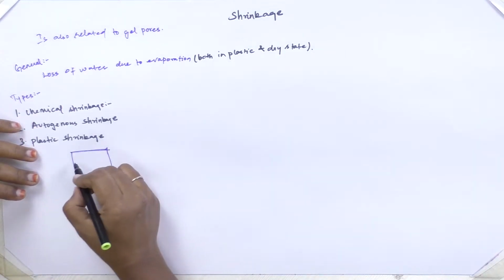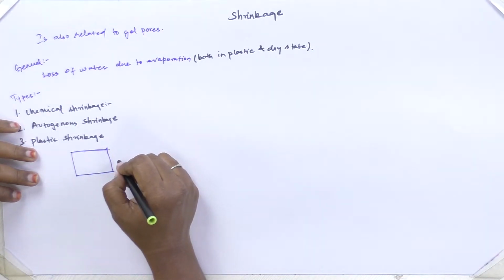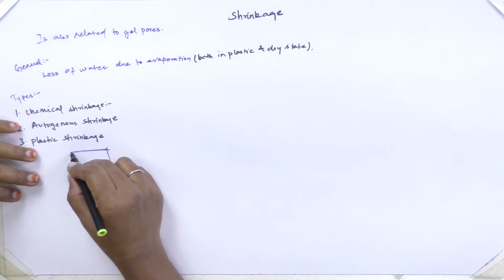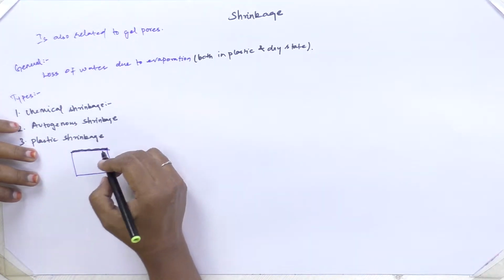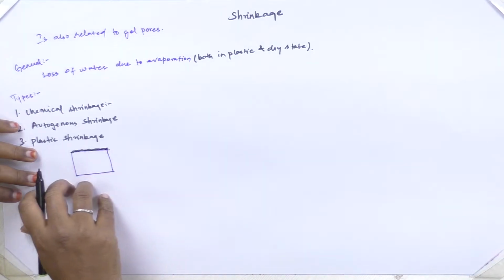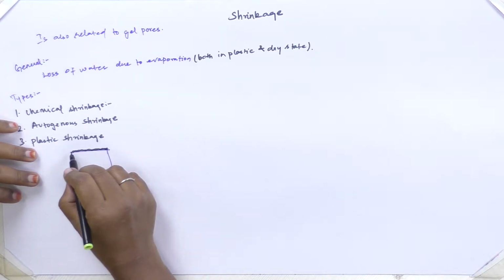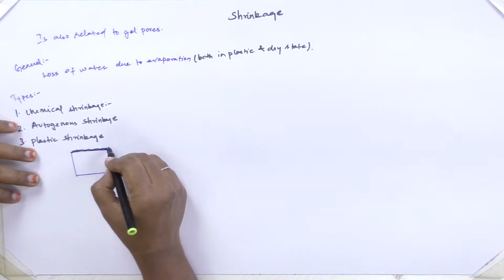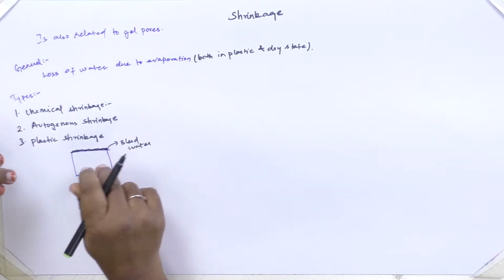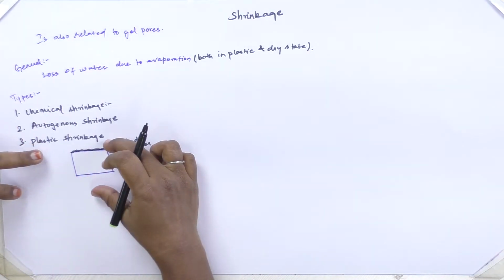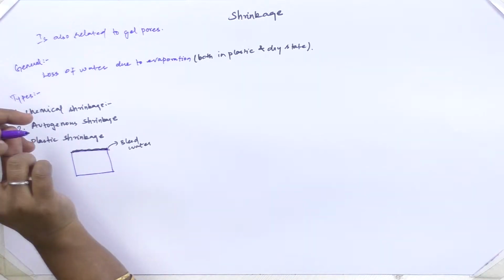After concreting, because of having a low specific gravity, the water will move up, leaving the aggregates and cement paste down, and if this bleed water gets evaporated, then there occurs a plastic shrinkage.